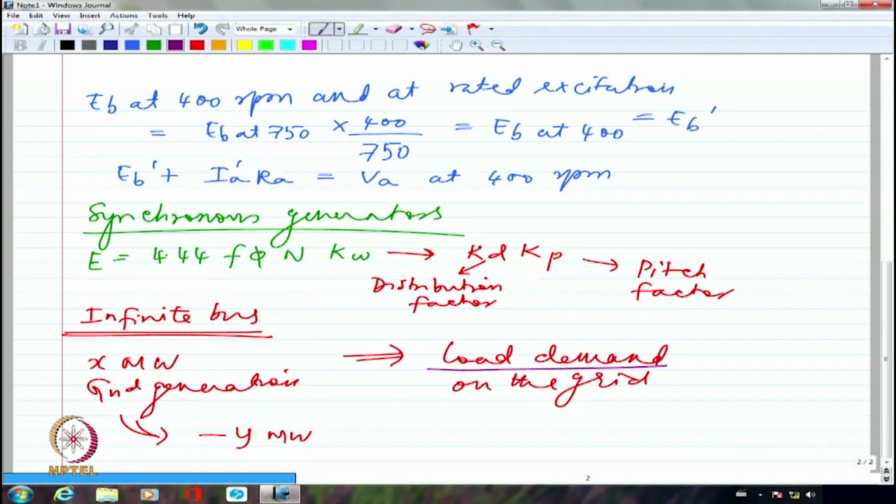They will not be able to provide more and more power than what they were providing. So slowly the kinetic energy that was stored in the rotating parts will be converted into electricity, and it will try to feed the load more than what it is capable of. But in the process, the speed will come down, definitely. When the speed comes down, the frequency will come down. If the frequency comes down, ultimately the grid will collapse. That's what happens sometimes if suddenly one of the complete lines conks out.